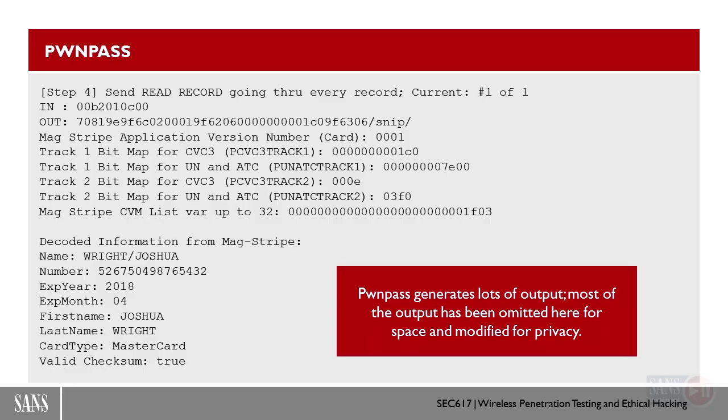We know how to do that. We know how to do TTL to serial conversion. If they have a USB, it's a serial to USB reader. So it's typically coming out as serial data from those readers. Okay. There's a set of tools called PwnPass to interpret the data coming out of those VivoPay payment terminals. So when a card is presented to the EMV reader, it formats and grabs all of the data, does all of the checksums for us, and can give us a whole bunch of information about the card.